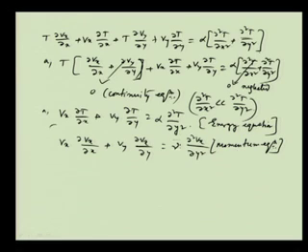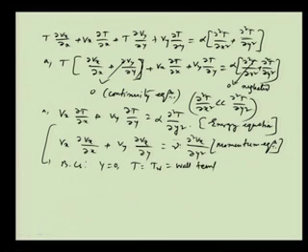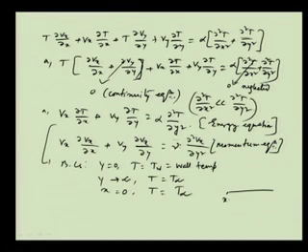Now, in case of the energy equation, we have the boundary conditions. At y equals 0, we will take T is equal to Tw, that is the wall temperature, and as y tends to infinity, T is equal to T infinity, and at x equals 0 also, T is equal to T infinity. x equals 0 means the leading edge, and the fluid is flowing like this. So, everywhere the temperature is T infinity, the free stream temperature of the fluid, and here is the boundary layer that is being formed.